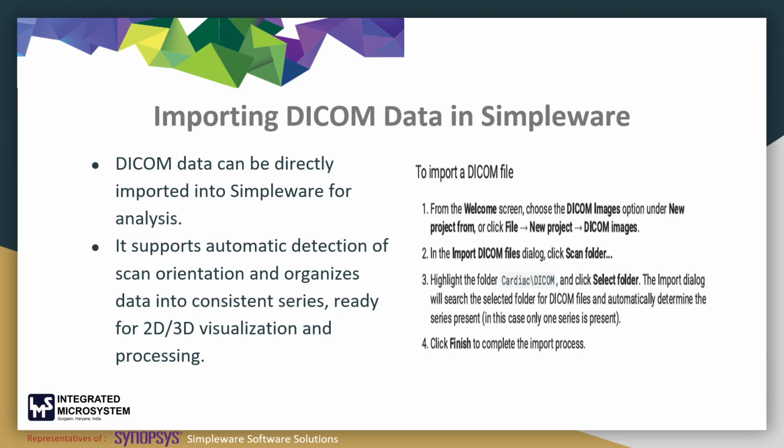So let's begin with importing data. Now that we understand the broader applications of Simpleware in cardiovascular domains, let's walk through the actual workflow. The first step in any modeling process is import. It is importing the medical scan data, most commonly in the DICOM format.